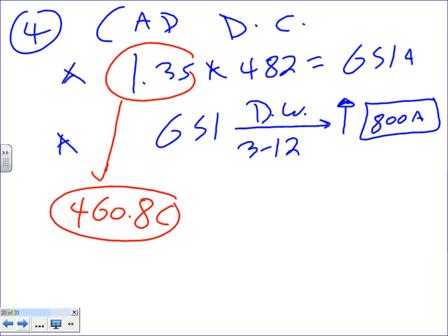But as far as you're concerned, when you go buy a 400 kVAR capacitor, you tell them you need a 400 kVAR capacitor, 3 phase, and they give you this big box. If you're buying a synchronous motor, you tell them that you need a 400 kVAR synchronous motor, and they'll give you this big synchronous motor. And then you install it the same way, guys. You need a disconnect, an overcurrent protection device, a conductor, to tie it to your system. I had a fuse, but it could also be a circuit breaker, guys. If you have a circuit breaker, then you don't need a disconnect, because your circuit breaker acts as your disconnect too.